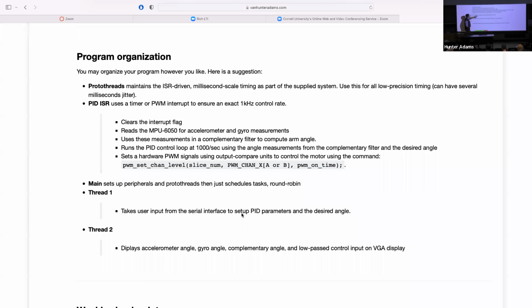And I mentioned that those repeating timer callback functions actually come not from a low-level hardware interface library in the CSDK, but from a high-level library that surrounds that low-level capability with a little bit more logic, so that just by using that low-level alarm hardware, it is implementing a repeating timer. But it's a slightly higher level of abstraction.